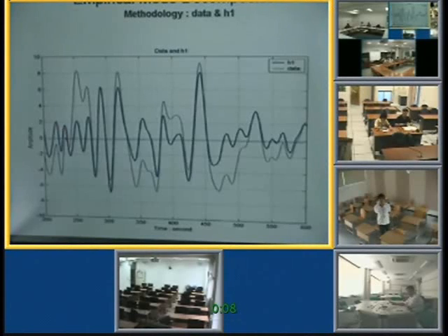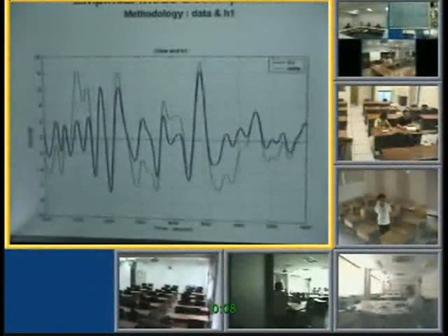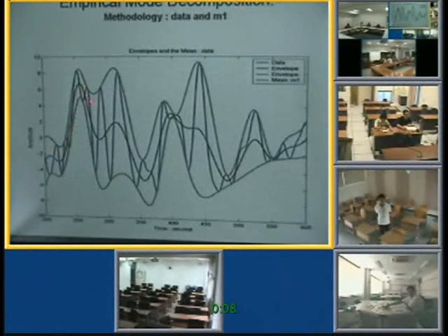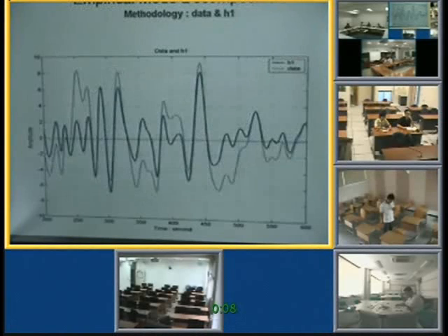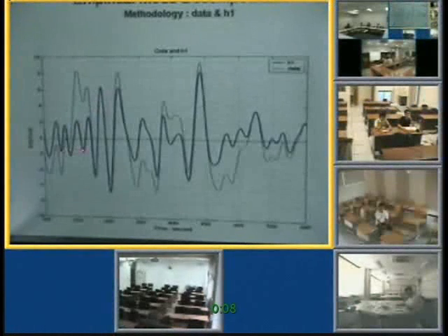And if the construction is correct, one consequence is that all the maximum of this blue line should be positive, because you see this line divides the maximum and the minimum envelope. All the maximum is on one side and all the minimum is on the other side. And if I move the x-axis to this line, maximum should be all positive, minimum should be all negative. And if that's the case, then I'm very happy, and I reach my objective. Now you see, all the maximum are indeed positive, all the minimum indeed are negative.